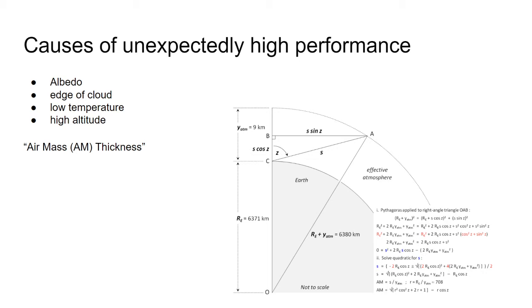We're talking about the raw power lines between the solar array and the inverter that need not just the typical 25%, but an additional 25% on top of that to account for the fact that there's more variables in a solar circuit in terms of environmental conditions than there is in a typical circuit in a building.